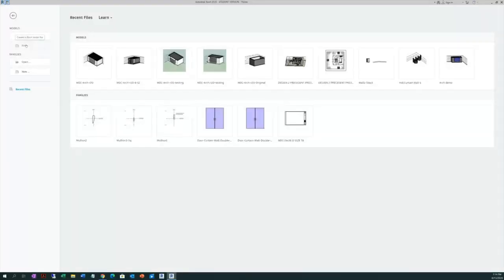Okay, now we are going to start a new project. That new project is going to be in a structural template, correct? So on the welcome screen, look for where it says New, okay? Then you are going to be prompted by this dialog, with Template file, Construction template, Create new project.